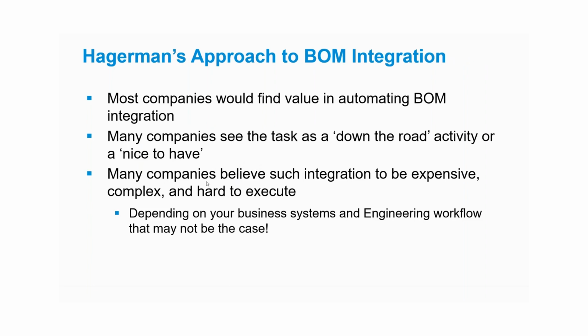Right. So let's talk a little bit now about Hagerman's approach to BOM integration. We've talked about the benefits, we've seen how you might do things manually. Let's talk about Hagerman's approach to integrating bills of material between your CAD environment and your PLM or ERP. I would argue most companies would find value in automating this. In some cases, when your BOMs are small and infrequent, it's not worth it. But if you're producing BOMs on a regular basis and they end up with even just dozens of rows, you'd probably find some benefit in automating this process.